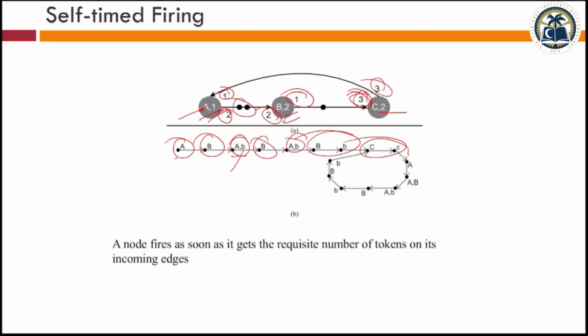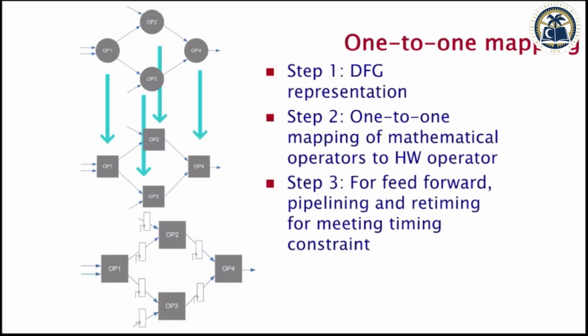Now there is a cyclostatic schedule which you can follow to run this algorithm. Initialization, and then you say now I am going to do this. So you fire C, C, then A, then B, B, B, B, B, B, and then again C, C, C. In this fashion you just keep on repeating if you have such an architecture. If you don't, then it is simple. You have operations in the flow graph, and for every operation you put a hardware operator.